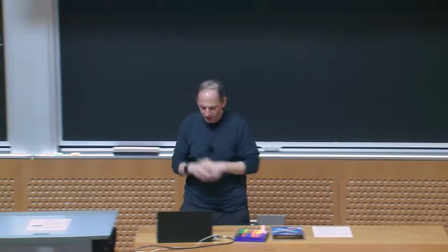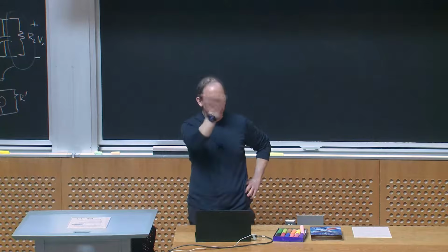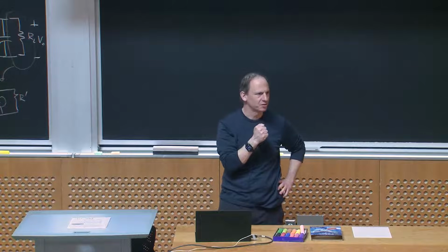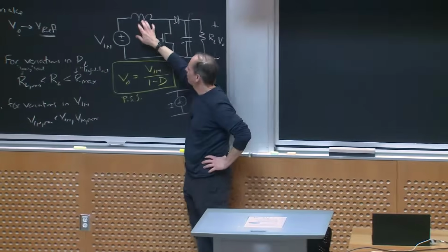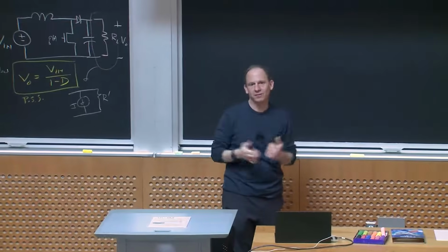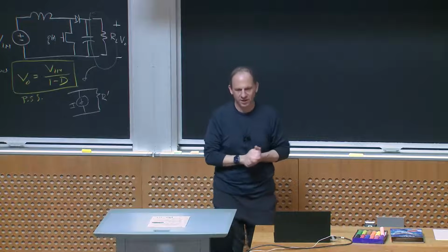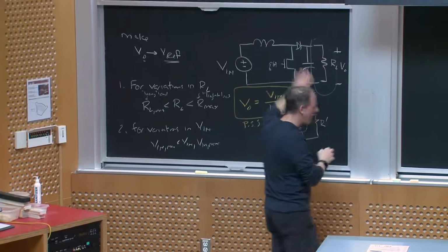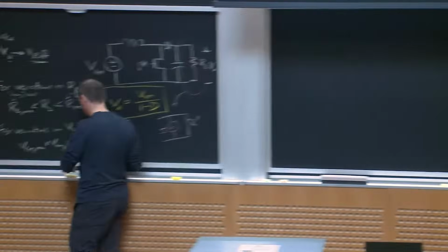And I'd like you to notice that this response looks sort of like a second order system, right? Kind of looks like a damped LC oscillation, which is not surprising, right? Because I've got one C and one L. And there's load on it, so energy's been taken out of it. So maybe that's not surprising. The question is, what does this thing look like, okay? So how would I control this thing in the real world? I'd use feedback control, okay?